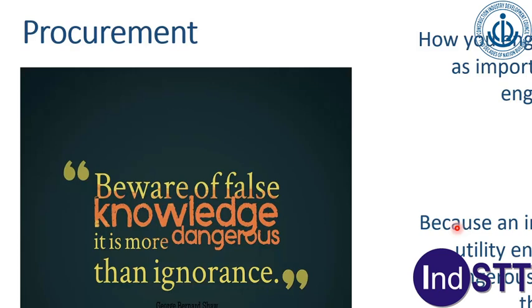Now, after going through this, again, I'll go to the same question. In your opinion, which is the most suitable, appropriate method or procedure to create accurate maps of underground utilities? Now, once I ask this question, around 96% of people finally say it's subsurface utility engineering. So it is not GPR, it is not ERT, it is not trenching, it is SUE.